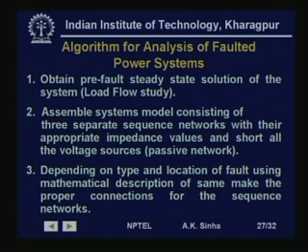How do we carry it out? So, what we do is we will write down the algorithm for analysis of faulted power system. What we do first is obtain the pre-fault steady state solution of the system, that is the pre-fault conditions. If we don't know or don't want to calculate these values, or we have an unloaded system, that is we have assumed that the system is initially unloaded, then of course, we know the voltages are 1 and the currents are 0.